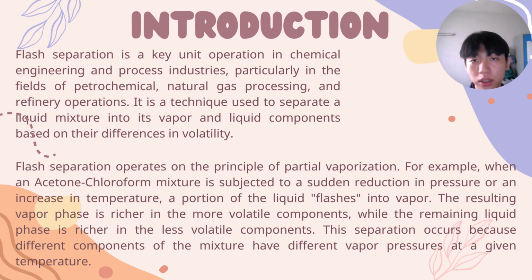Firstly, I will talk about the introduction of the flash separation. The flash separation is a key unit operation in chemical engineering and process industry, particularly in the field of petrochemical, natural gas processing, and refinery operation. It is a technique used to separate a liquid mixture into its vapor and liquid components based on their different volatility. Flash separation operates on the principle of partial vaporization.